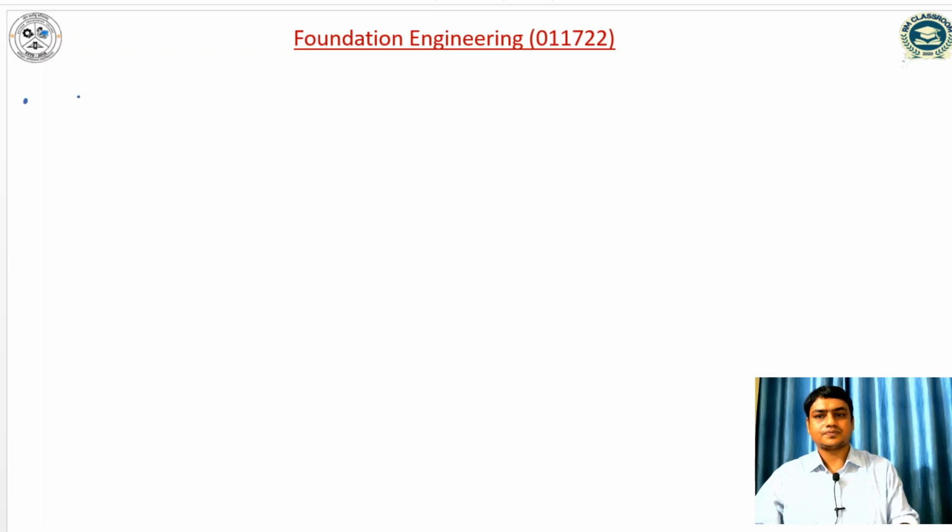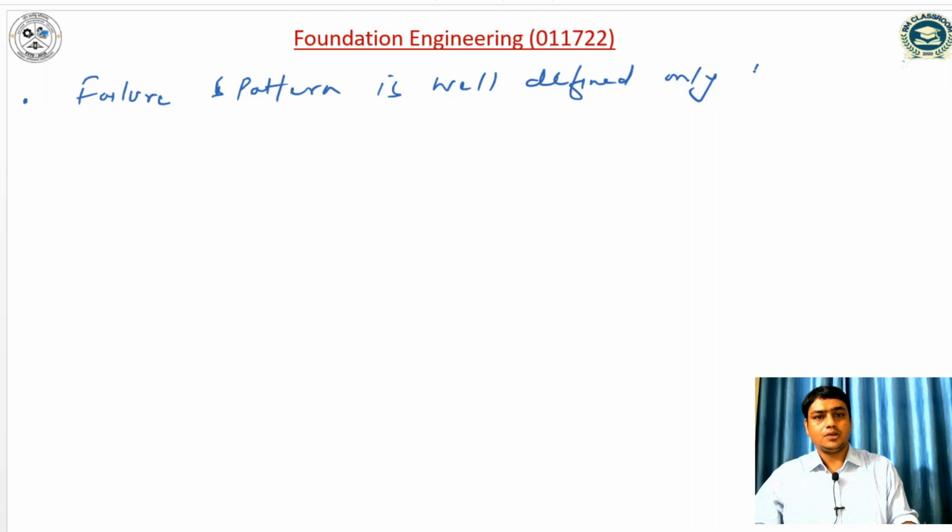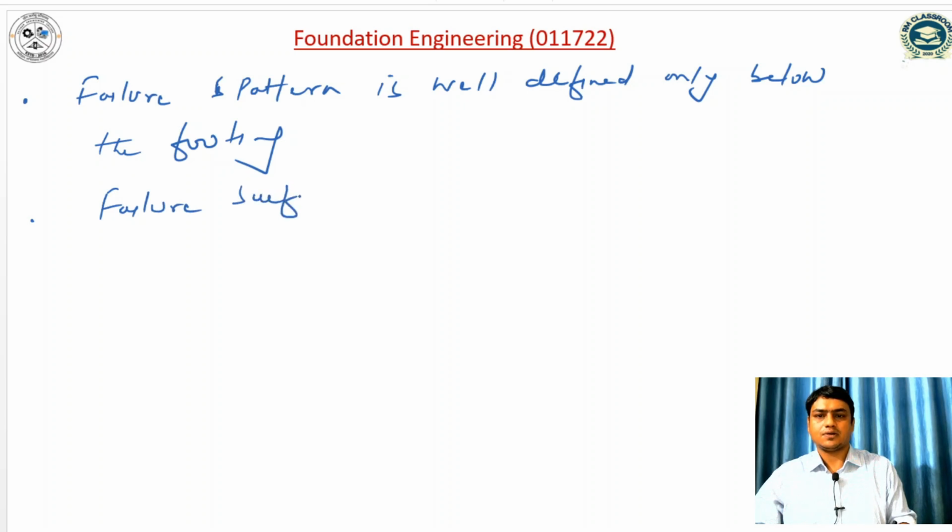Third property is failure pattern. Failure pattern is well defined only below the footing. Failure surface will not touch the ground surface.